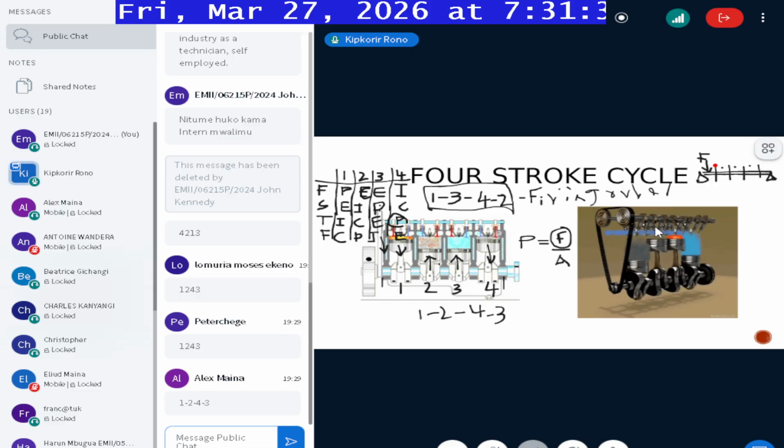So if you had a force, the firing order being 1, then 2, 3, 4, 5, like that, depending on the number of cylinders, it would create a lot of undue stress on the crankshaft. So the stress needs to be distributed in a certain manner such that it does not build up on a single section of the crankshaft.